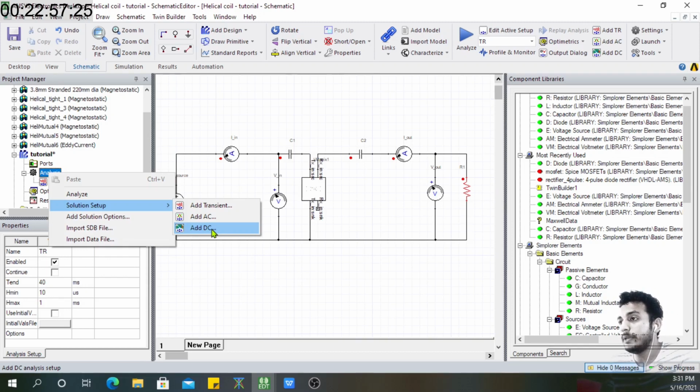So maybe in an arbitrary way, when I put the value of C1 and C2, right now I have kept that at 100 picofarad, it's still resonating at some frequency, okay? But we do not know what frequency it is, and we do not want to be at that frequency. We want to shift that resonance from that arbitrary frequency to 6.78, and that can happen only when we change the value of C, because that's the only variable that we have right now.